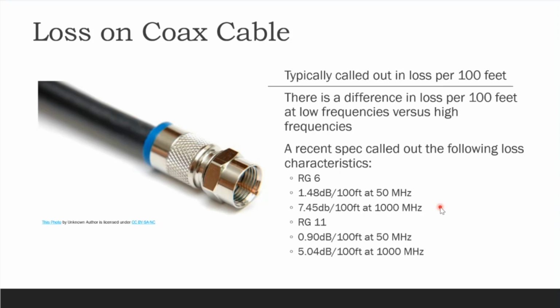1,000 megahertz is up at the high end of that range. It's a very high RF frequency, and it gets used sometimes. We don't see a ton of broadcasters still using frequencies up that high, unless it's more of a residential application. In most commercial applications, you're not going to get up to 1,000 megahertz from the broadcast side of things.